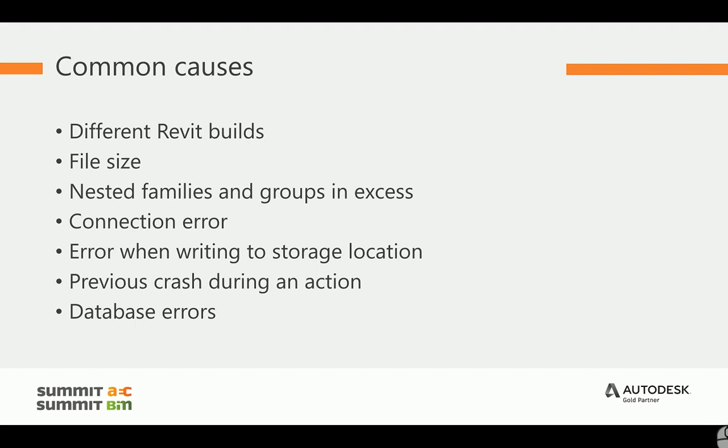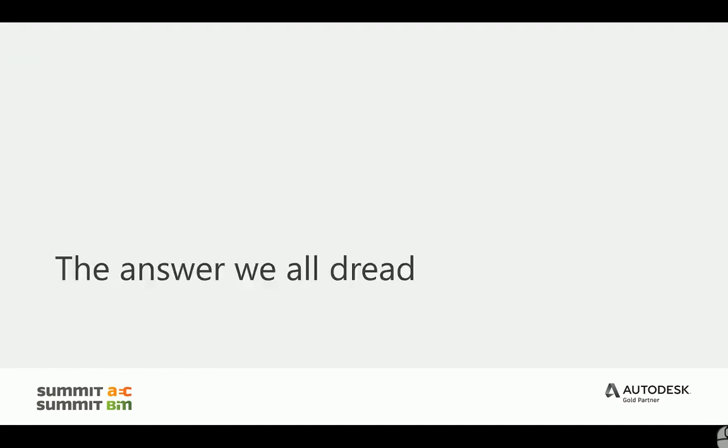Databases that are incorrectly modified. Sometimes these errors are the result of an add-in, and even specialty fonts. These cause instabilities in the file, which can result in crashes and the inability to complete some of the following actions: sync, save, audit, purge, open and create new view, editing objects, accessing VG overrides, even opening the file.